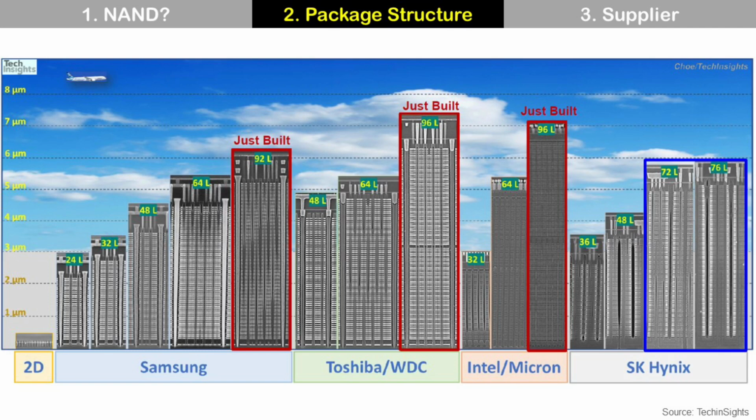Not to damage these memory cell layers in 3D NAND, companies are considering plasma wafer dicing, which is a special wafer sawing technology. The memory layers of 3D NAND go up to 176 layers. In November 2020, Micron announced 170-layer 3D NAND, followed by SK Hynix in December 2020. In February 2021, Kioxia announced 160-layer 3D NAND.